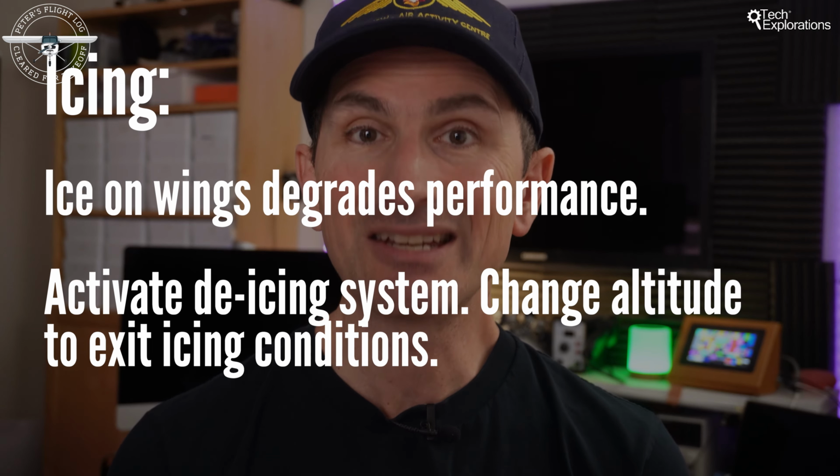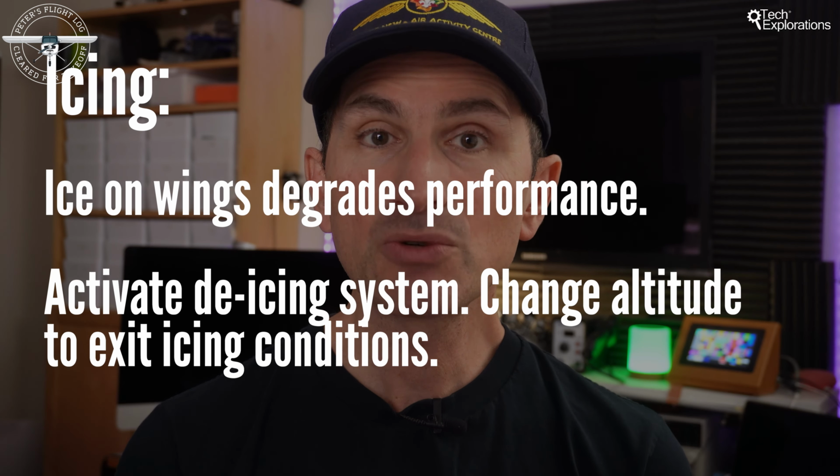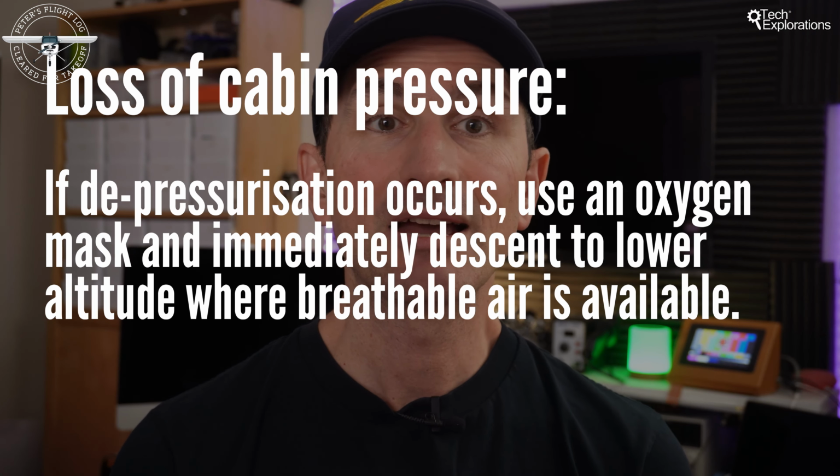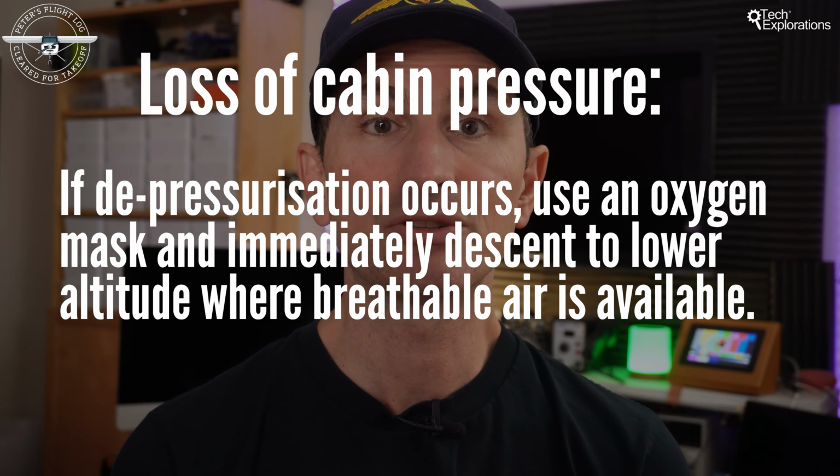Icing conditions. Ice accumulating on the wings can significantly degrade performance. The initial steps involve activating the aircraft de-icing systems and changing altitude or course to exit the icing conditions. Flying in Australia's Mid-East, it's very unlikely that I will ever face this situation. Loss of cabin pressure. In the event of cabin depressurization, pilots put on an oxygen mask and initiate an emergency descent to a lower altitude where breathable air is available. Luckily, perhaps, the Cessna 172 does not have a pressurized cabin, so that's one less thing for me to worry about.